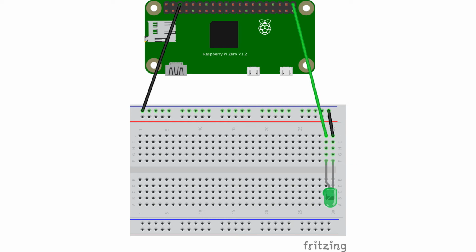Now, just like with a circuit, you're going to have to go negative. So you're going to take a black wire, which usually represents the negative, and in this case, the short black wire is best, from J30 to the blue line in the breadboard. Electricity is going to travel down that blue line till it gets to a long black wire, and that's going to plug into the first row. Then the other end of the black wire is going to plug into the ground, which is where the negative terminates.